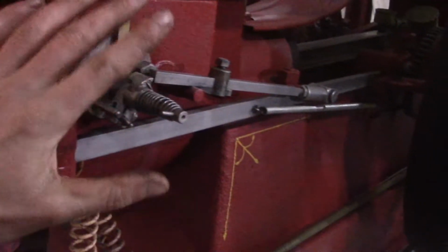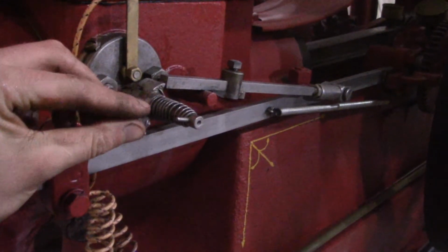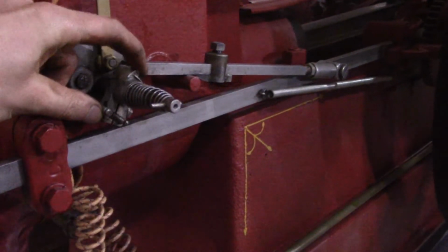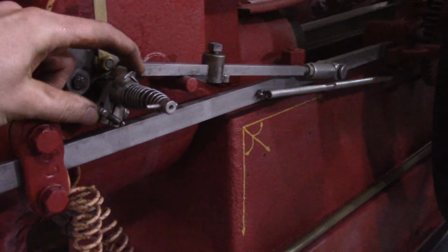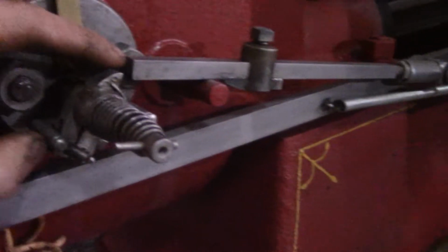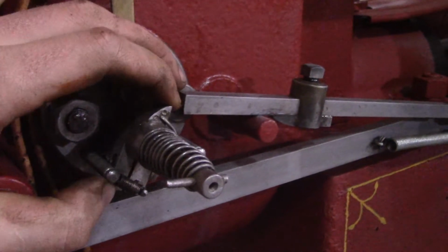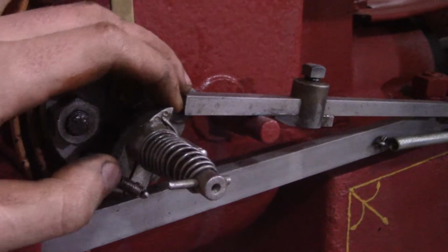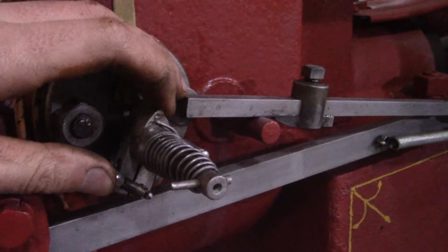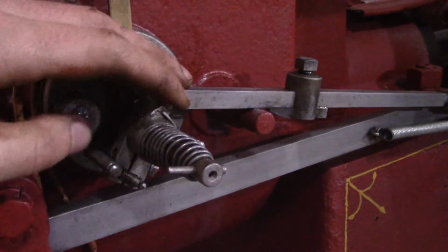I'm not going to take this off to show you the contacts themselves because I would ruin that gasket. I don't feel like making another gasket, but I'm sure all of you have seen points before. They just open and close, make and break contact, and that's all that's going on inside. Now this particular igniter has two sort of different movements. There's this little bit of movement. It'll move freely and then stop, and then just the top part will turn, but it is held back with this very heavy coil spring.